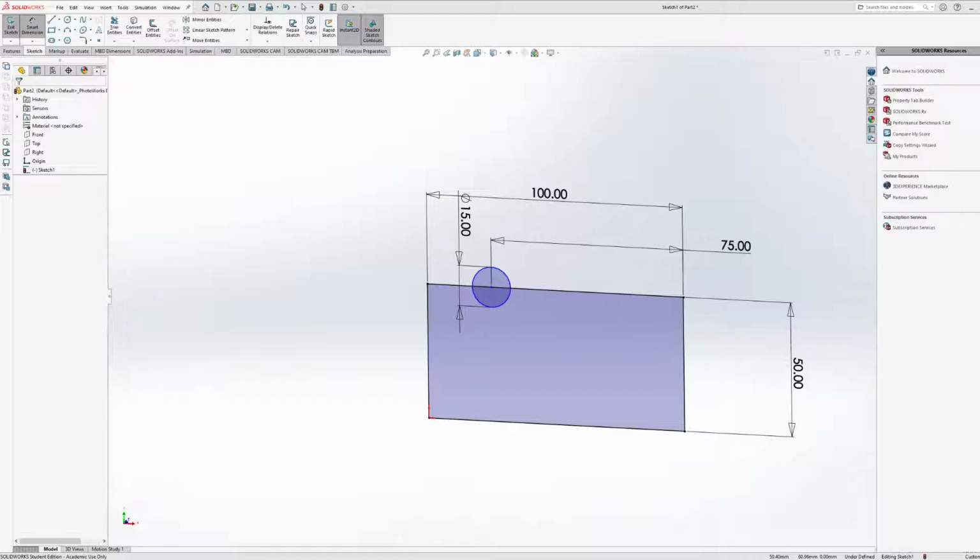So more so what I'm trying to say is don't be so concerned with those measurements. Make sure that the measurements of your sketch are correct, just because trying to smart dimension things once it has already become a 3D figure tends to be a little bit trickier.